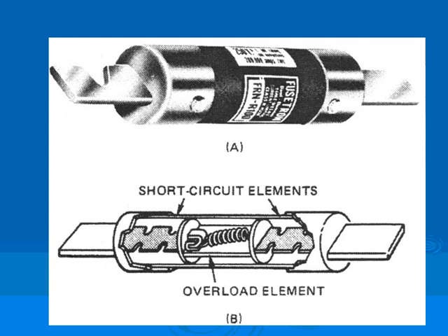When it comes to fuses, guys, you're familiar with the different types of fuses. The famous one is the dual element time delay fuse. A dual element time delay fuse is almost a circuit breaker. You can look at the overload component and the short circuit component. So they have two components on them. One will melt upon the existence of a short circuit. One will melt upon the existence of an overload.